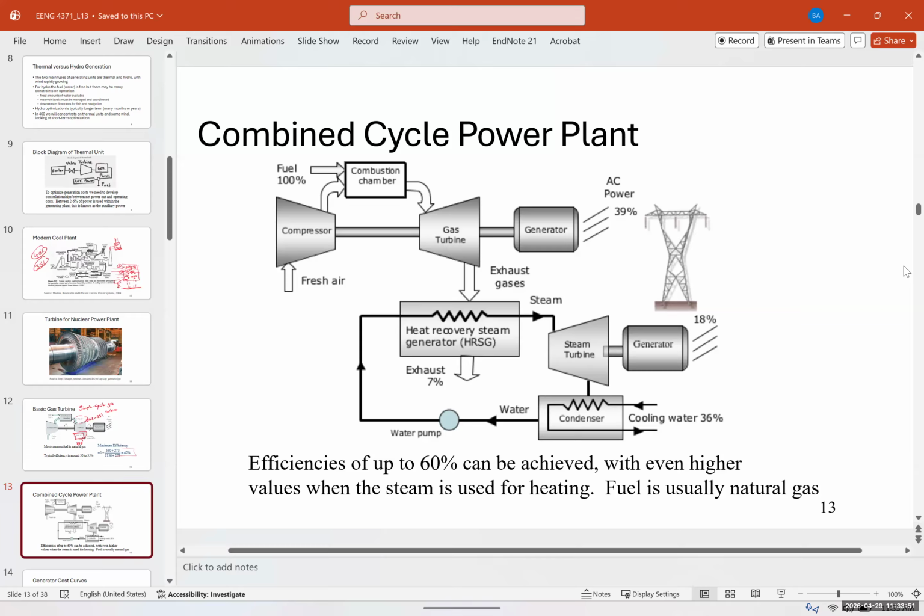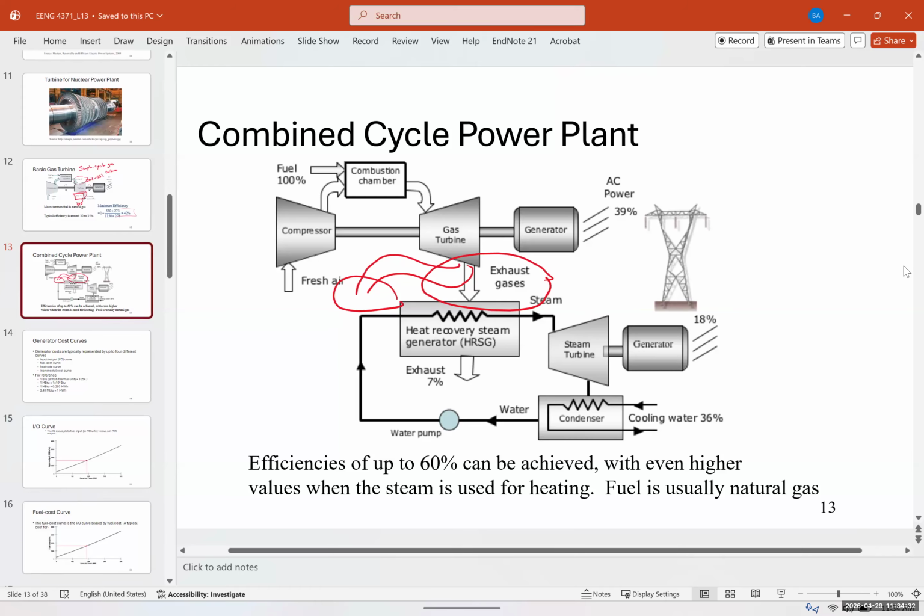One thing that is very beneficial, and I've been in a couple of these type of power plants, is between these two, the exhaust gas, you have control over it. So if you want to cut back on power, the only thing you need to do is just exhaust this gas outwards. So don't direct it to the steam recovery system. Just exhaust it, and then you suddenly cut your power generation in half. So with the easy switch of a switch, you can just exhaust that heat outwards and shut down the second generator, which sometimes is beneficial when you have a lot of excess power.